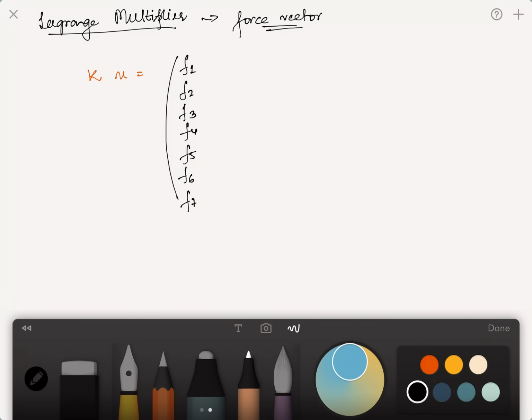and the same MPC was applied, that means U2 minus U6 is equal to 0 was still applied here, then we would actually add, remove, let's say add, remove to make a balance of the forces. So we would reduce a certain term lambda, a certain Lagrange multiplier lambda, from F2, and we would add the same Lagrange multiplier to F6 because the relation has to do with U2 and U6. So those are the nodes where I need to have an appropriate constraint force to mimic the situation.